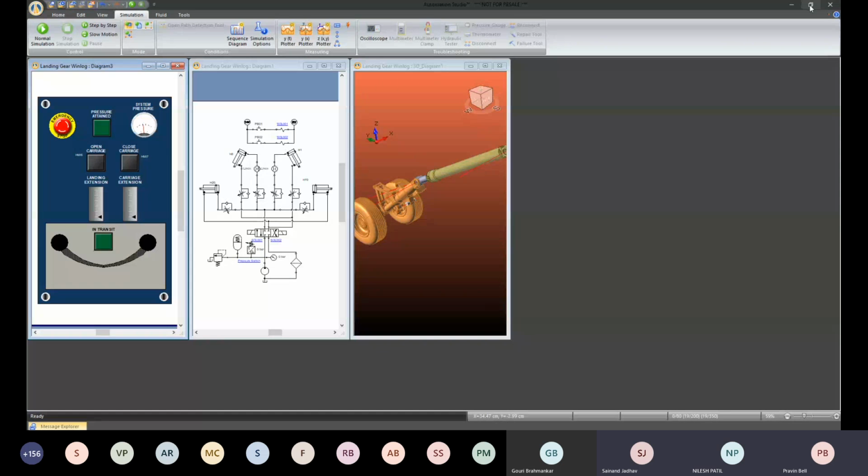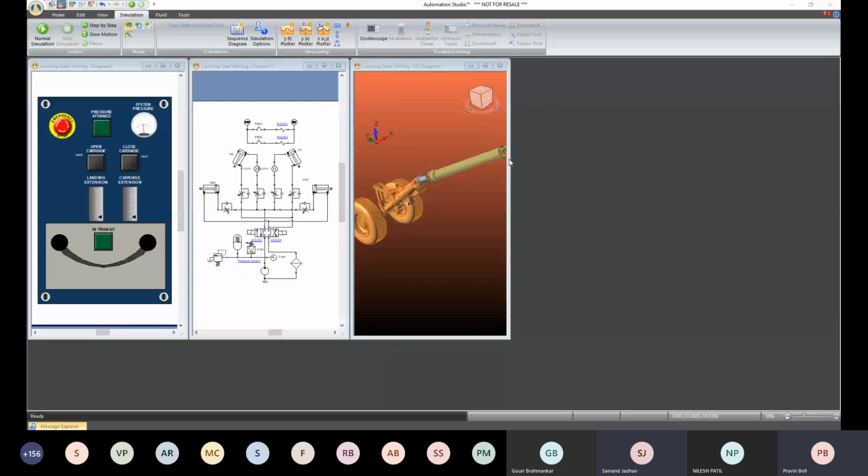Yes. Okay. So in OPC, what we do is, in the background, which I could not show you, there is a small OPC server which is running. In that OPC server, I defined data tags like analog 01, analog 02, analog 03, boolean 1, boolean 2, boolean 3. That OPC server acts as a communication server, so data can be sent to the server and can be read from that particular server.